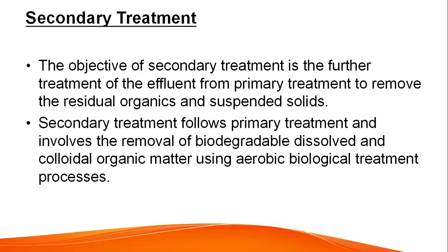Secondary treatment. The objective of secondary treatment is the further treatment of the effluent from the primary treatment to remove the residual organics and suspended solids. Secondary treatment follows the primary treatment, and it involves the removal of biodegradable, dissolved and colloidal organic matter using aerobic biological treatment processes.